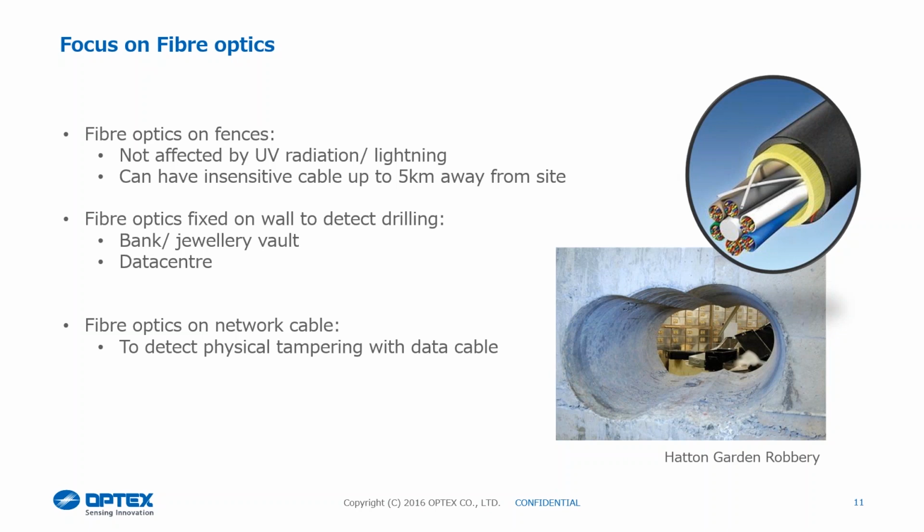And then moving on, the last part of that technology is what we can actually do with the fibre sensors, which is secure fibre optic networks running into buildings. So if you've got a data center that's got perimeter security around it, you know nobody's going to get into the building. What you don't know is if anybody's going to try and attack that incoming fibre that's coming into that data center by lifting a manhole cover somewhere and then attacking it. What we can actually do is use fibre optic cables to make sensing zones. So somebody gets the lid off the hatch, then goes to try and attack the cable, whether that be maliciously damaging it or trying to tap information out of it, then we can give you an activation when somebody starts interfering with that cable. So moving on to the next slide.